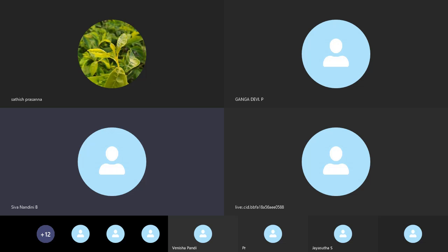So go to slide number 15. This is an example schematic diagram. What are the components available in this schematic diagram? Here we have a PIC microcontroller IC in the center, and at the top a switch. That switch is the start switch, and at the bottom that circle represents a 3-volt button battery. On the right side you have LEDs and a resistor.